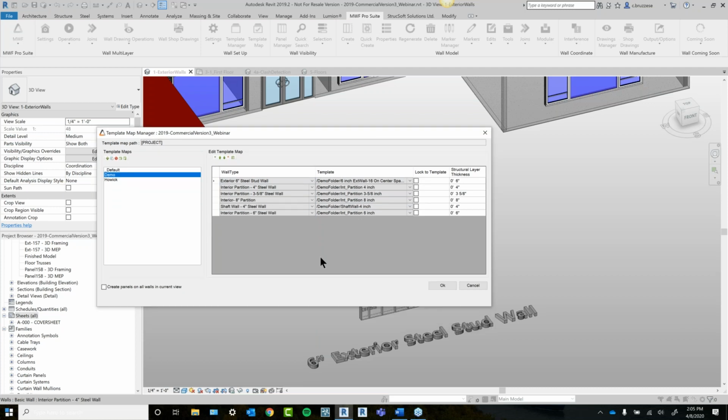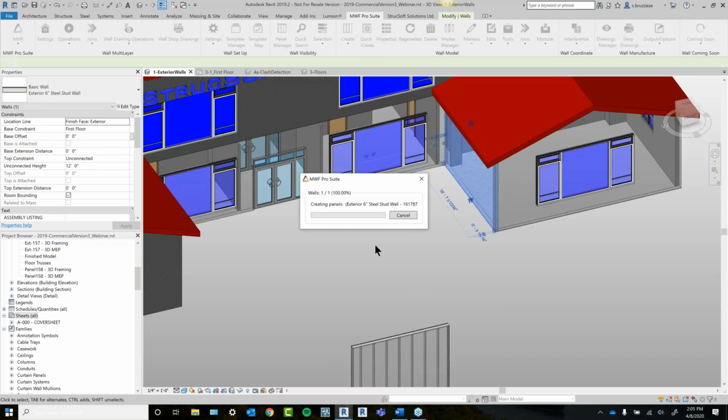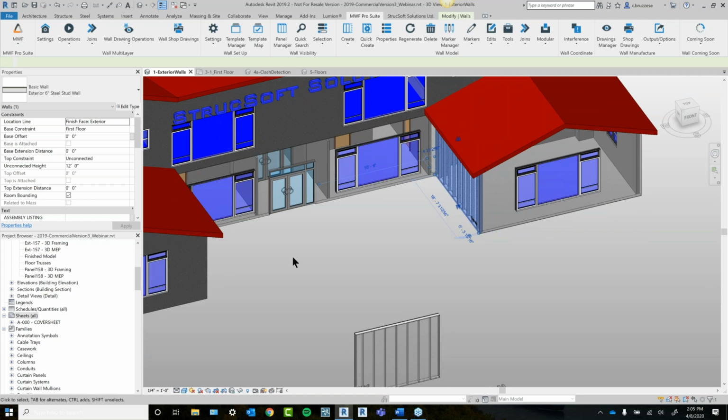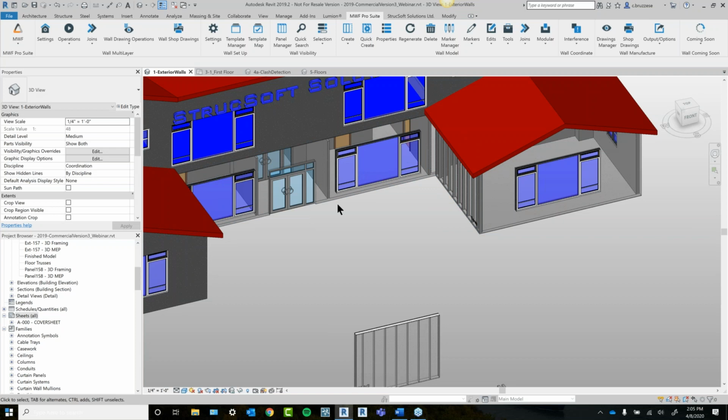So once this map is activated, I have everything good to go. That's when you can go ahead, grab a wall, and use this quick create command. So because it's framing out according to that map, this is something that's going to enable you to mass select a bunch of walls in your project, say create, and it'll frame out regardless of what template you're using, save you from having to go into each individual wall and choose which one you want as active.